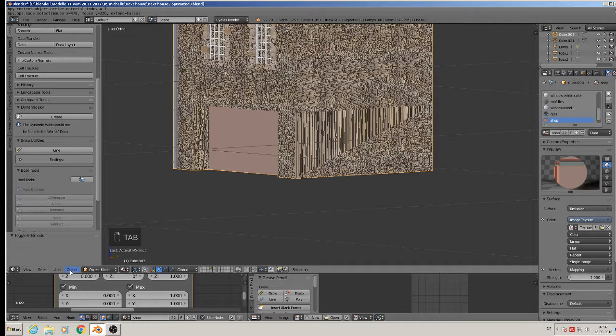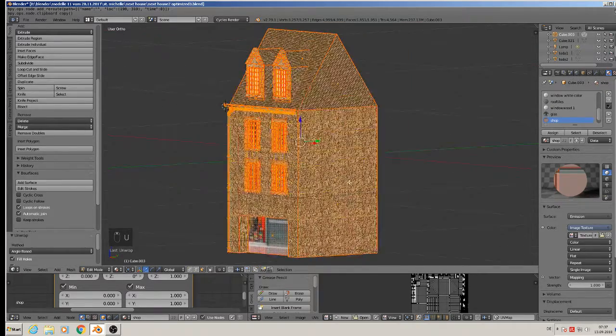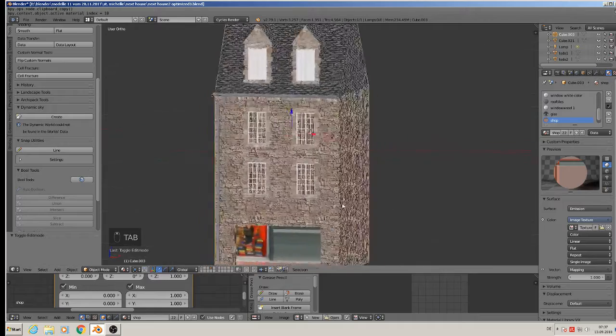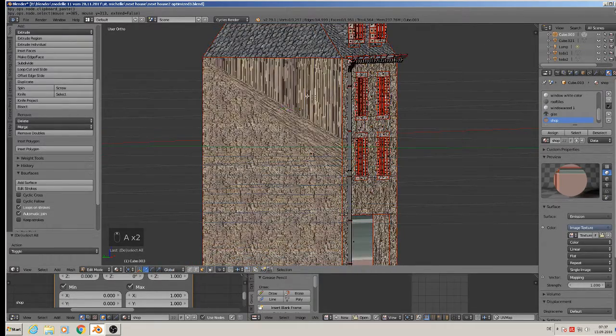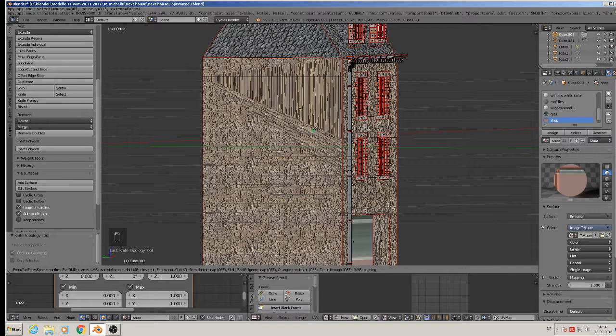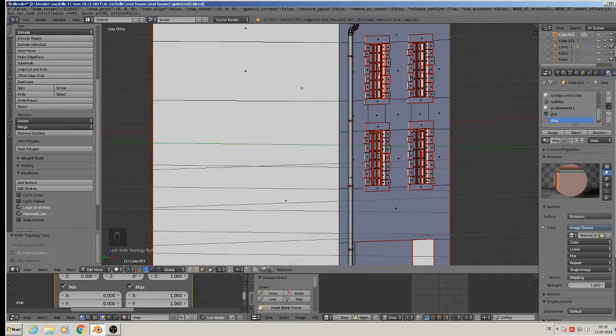So we have to again select the object, apply rotation and scale, and UV unwrap. Now you see here it is a clean one, here that isn't, because we must cut here also. So from that point to that point, spacebar to cut, knife from there to there to cut, and from here, see it, all lines that come from here have to go through there.